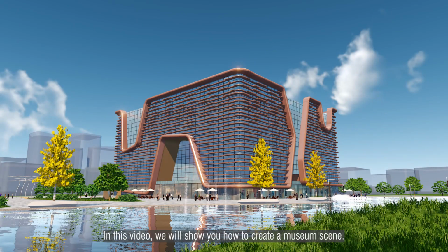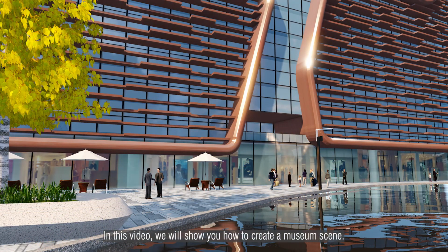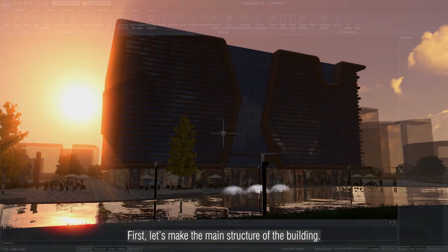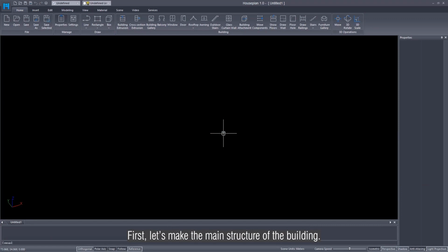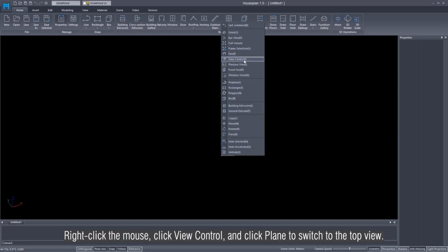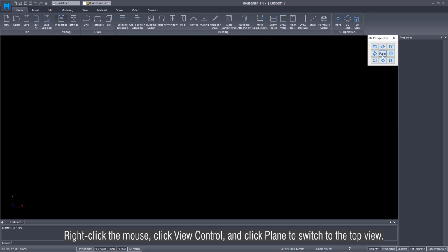In this video, we will show you how to create a museum scene. First, let's make the main structure of the building. Right-click the mouse, click View Control, and click Plane to switch to the top view.